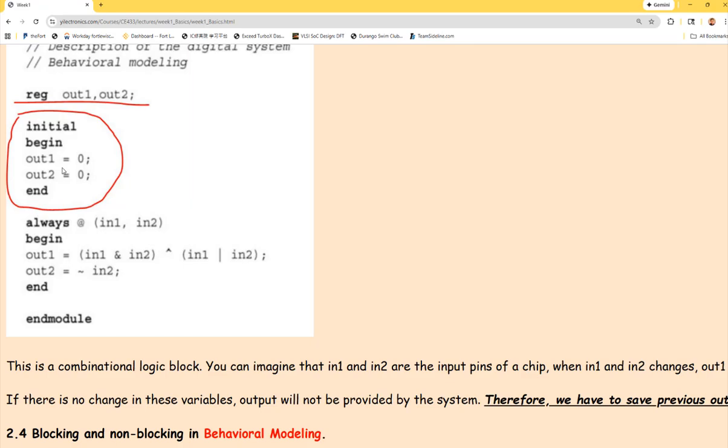But also there's a difference between synthesizable and non-synthesizable Verilog. Synthesize means it converts your Verilog into a netlist, which is used for hardware design. So some of it is synthesizable. If you are targeting a chip, you have to make sure that your Verilog is synthesizable, okay? Sometimes it runs in Vivado as a simulation. Sometimes it just doesn't work if you want to synthesize it into hardware.